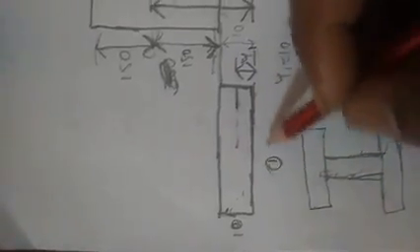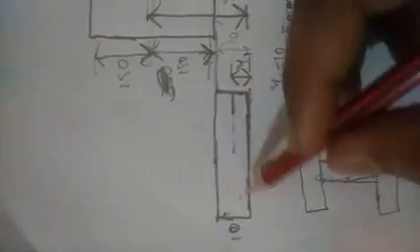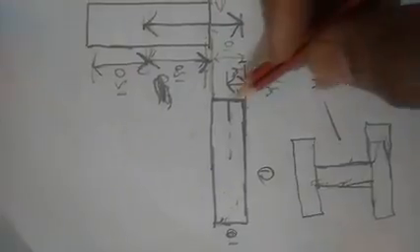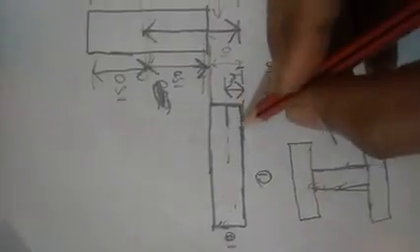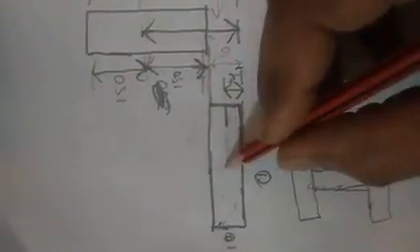Now y1 you have to determine. See here, the height is 10 and the length is 300. This is the first section, so there is no need to consider the length; you need to determine the height, from the center of this section to the reference axis. For all 3 sections you have to take a common reference axis.